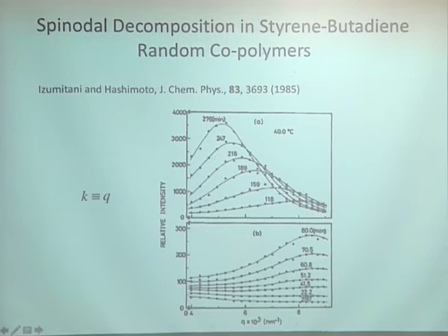And so this is the wave number with the maximum growth rate. This is exactly what the linear theory of spinodal decomposition would tell you. Then at later times, the fluctuation with the maximum amplitude begins to shift to lower values of k. And this is this nonlinear regime that I'm talking about. Once the amplitude becomes too big, you get nonlinear effects that move this.